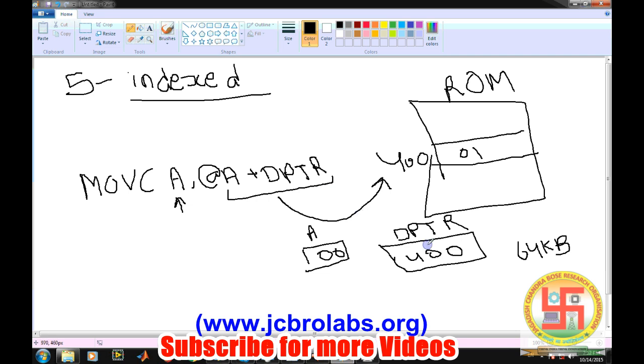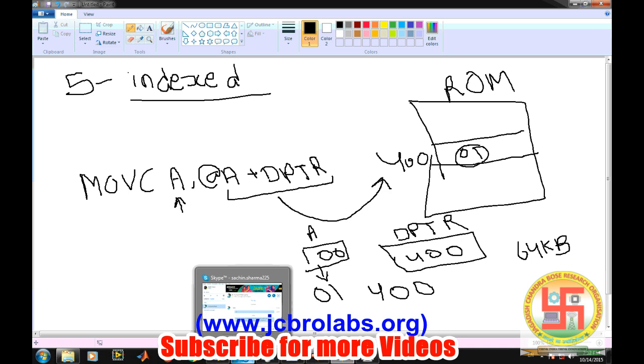At that address, 400 plus 0 equals 400. So at the 400 memory location, whatever is written, move that into the accumulator. So the content of the accumulator will change to 01. This is how indexed addressing mode works.